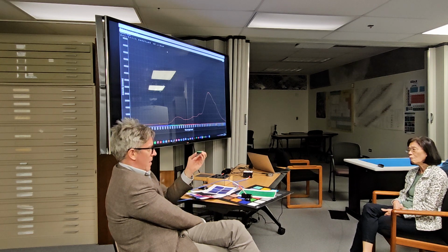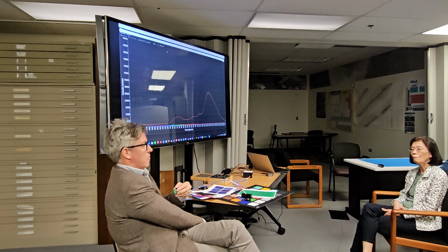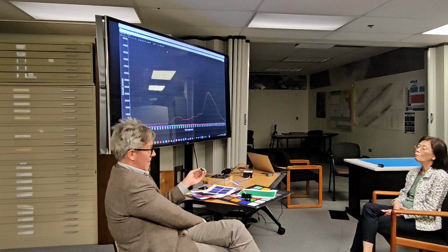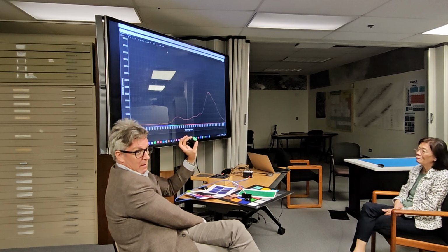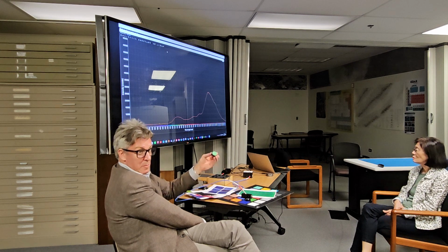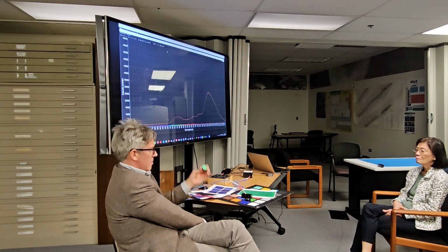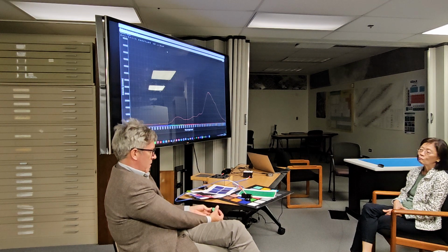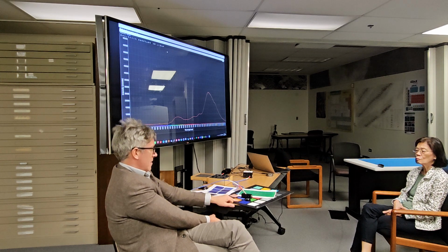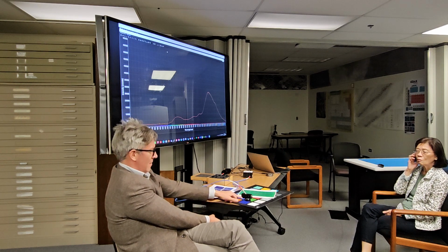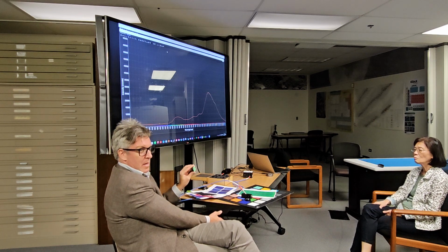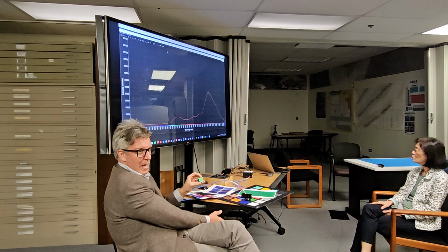So if we have a calibration source, so if I'm building a spectrometer and somebody at Brown is building a spectrometer, and we want to make sure our spectrometers are telling us similar things, I can put that in the mail and send it to Brown, and they can make their measurements, and then we can agree that our instruments are producing similar results. This is pretty stable over time. I mean, you don't want to touch it, but if you touch it, you just use some wet sandpaper to rub off the surface. This thing's okay for a few $100, but this isn't going to last forever, and it's going to change over time. So these are kind of expensive because they're kind of stable and they can be calibrated in a lab.